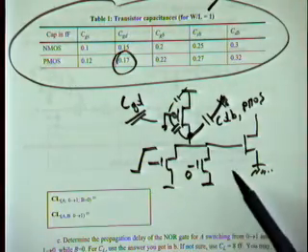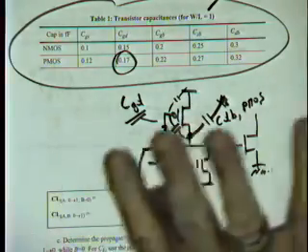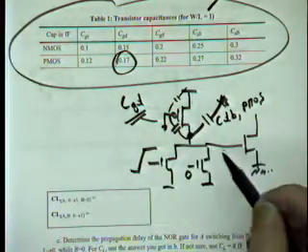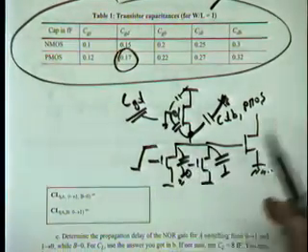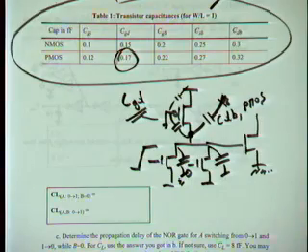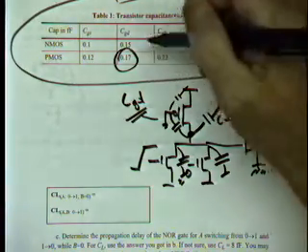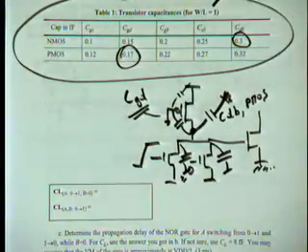Now let's look at the NMOS, and there it's a little bit trickier. I have two transistors here in parallel. Obviously, for both of them, I have to include the drain to bulk capacitance. In both cases, I have drain to bulk sitting there. We linearized it. We have the value here. Drain to bulk, it's 0.3. And depending upon the size of the transistor, we have to multiply this a little bit upwards.